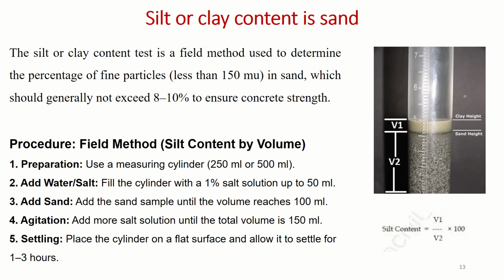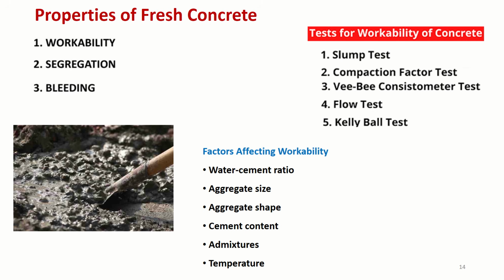And that clay content should not be more than 5 to 10%. If it is more than 5 to 10%, such a sample should be rejected. So that is the IS requirement. Now the next test is the test on fresh concrete.